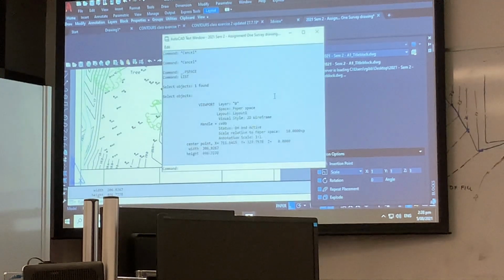Now when I'm checking your drawings, I set that to 9 decimal places. And if you are 10.00001, or you're 9.999999, you will see on your marking on the right hand side a little wee red mark called minus 1 for each viewport. Okay? So before you copy it, make sure it's the right scale. Trying to get you into good industry habits.